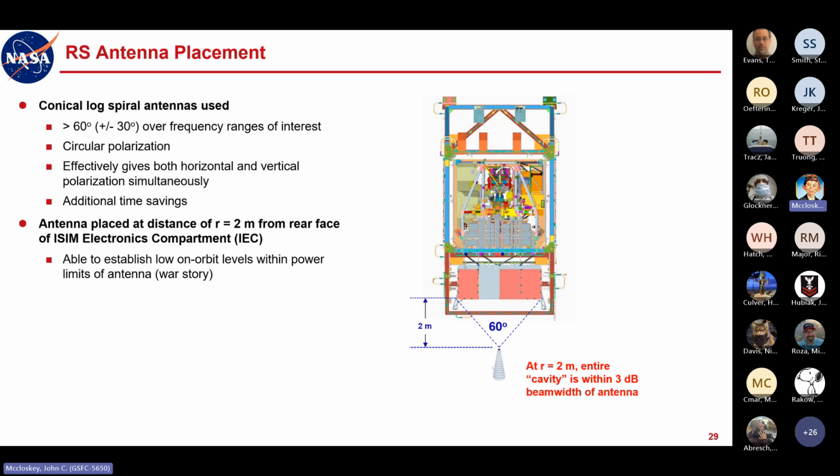Had we done the calculation beforehand, we would have seen that we needed a bit more than 50 watts. I don't think it was a lot, maybe 55 or 60 watts. It wasn't like we were putting hundreds of watts through it, but we needed a bit more than 50 watts to get 20 volts per meter. And the antenna didn't like that. It got a nice brown tip, and it was hanging in the EMI lab's wall of shame for a while.